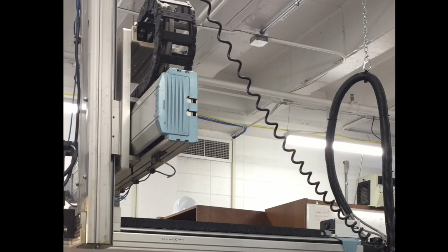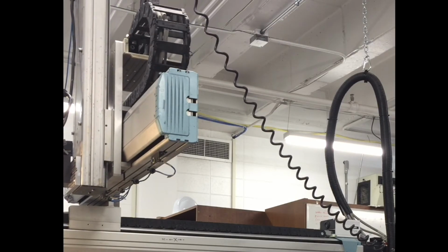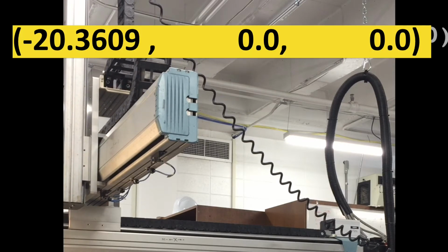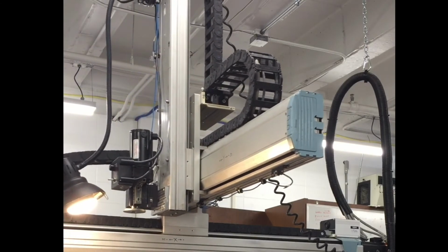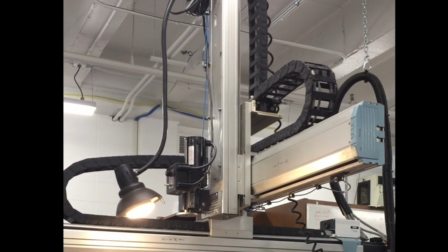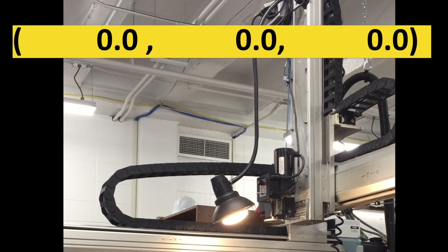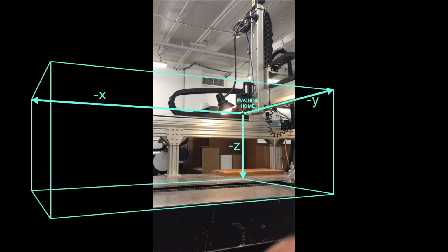It starts by moving in the positive Z direction to Z0, then moves in the positive Y direction to Y0, and last it moves in the positive X direction to X0. That's called machine home. Now let's take a look at the work envelope. For the machine to get back into its envelope, it has to move in a negative direction in all 3 axes. And the work envelope size is limited by the extent of travel of each axis.